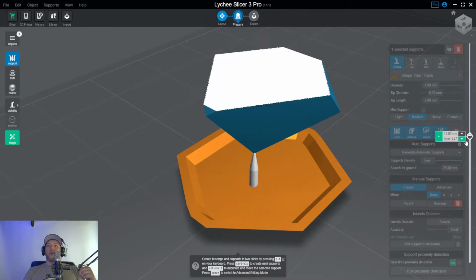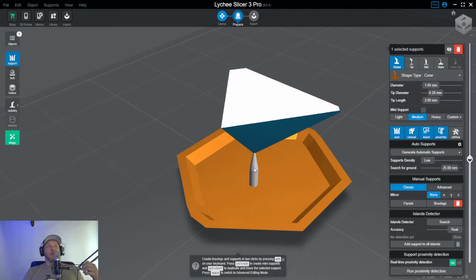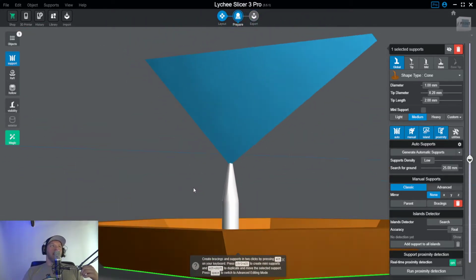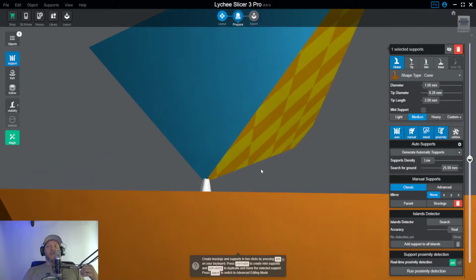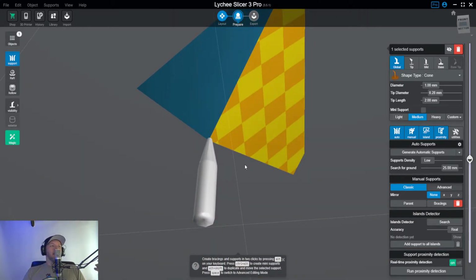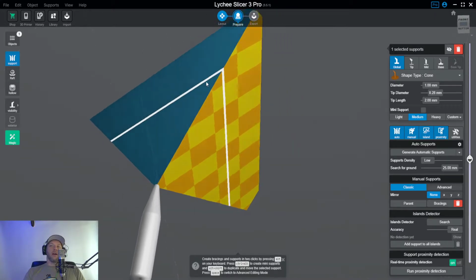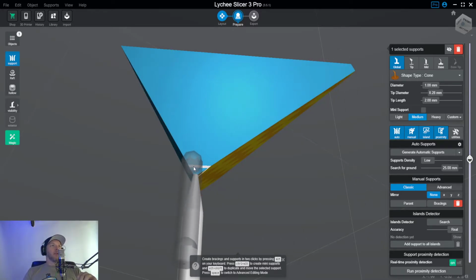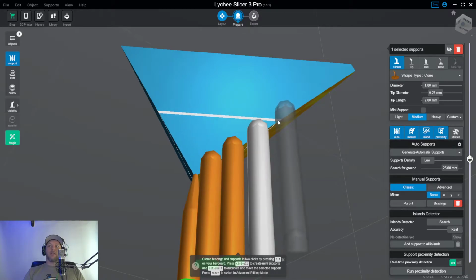And once we get to the center part where we've got a really wide surface area, that's going to pull it right off the top of that support, but we're off to a good start. So here's my tip, and you guys who are experienced probably know this already or already do this. This is what I refer to as chasing the edge. I think I made that term up. Maybe I heard it somewhere. I don't know. But the way I always approach this is if there's a hard edge or a definitive edge to the model, it doesn't have to be sharp like this, but some sort of line to follow, that you would want to maintain the shape of, I will always follow that edge all the way up.